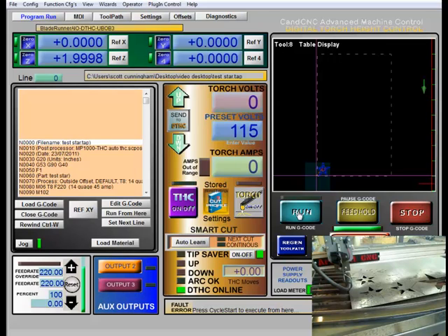So you notice that it did it again. It cut out my torch mid-cut, then turned it back on. One more reason, never use Windows 7 to try to run your plasma cutter. There are just too many quirks in it. And that's that. And there's just one more reason also. You want to have as little running when Mach is running as possible. Because having screen capture software and HD video camera is probably giving me some problems.